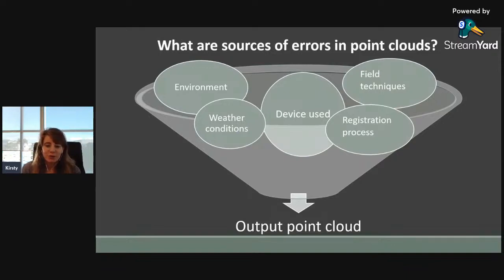Weather is also a big issue for drones. On a drone, the internal barometer can be affected by the wind or the humidity conditions, and that can cause up to 30 millimeters of error in the drone's recording of its flight direction and altitude, and that then affects the reconstruction of any data from it. So the positions of that airborne LiDAR or overall pictures will be off.